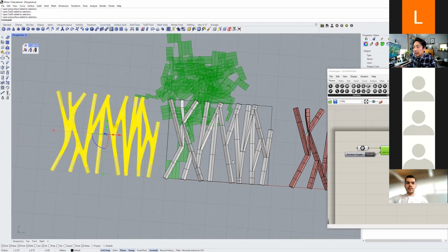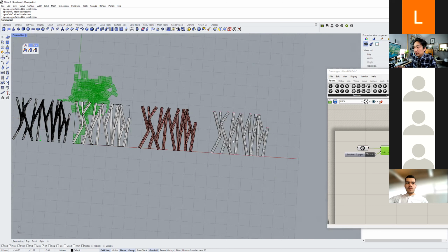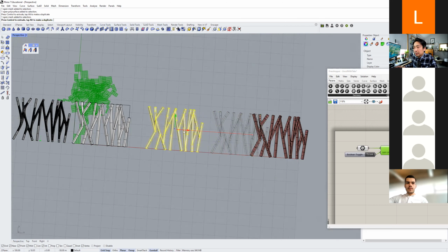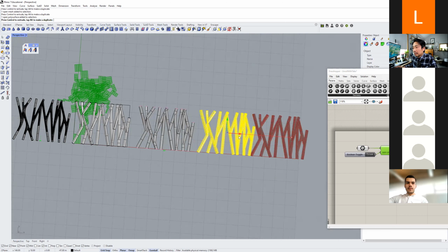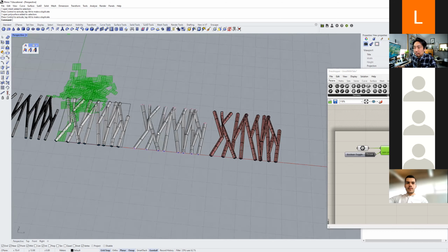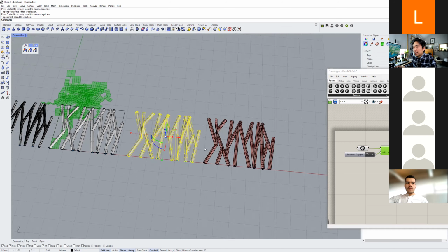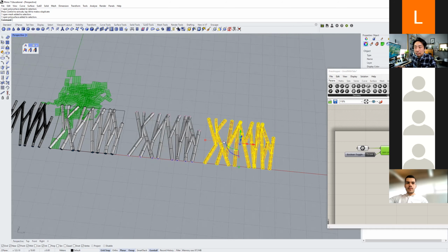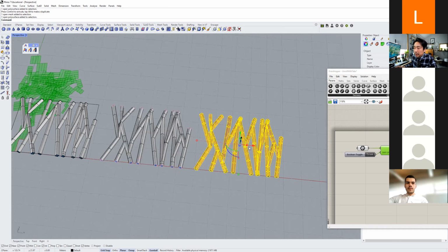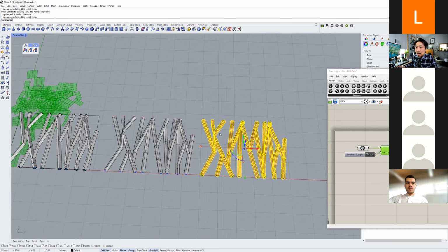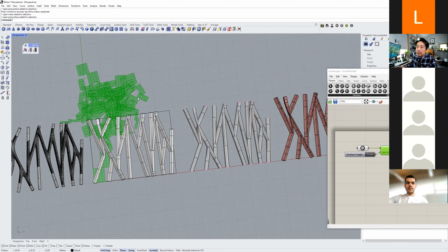Now I extracted the control cage into a mesh, because that's what Rhino does: it only gives me extract mesh from control polygon. Then using the mesh to NURBS function, I created the BREP object back from that. And doing that makes this unrollable.